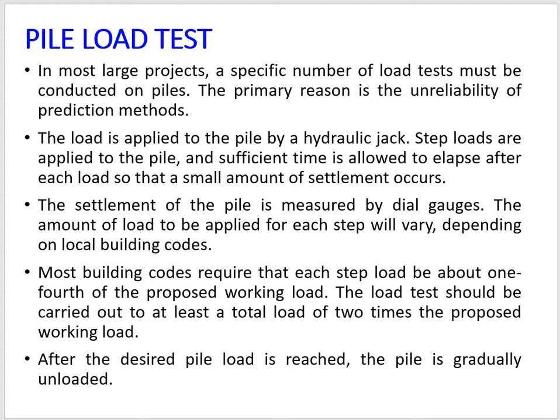In the field we have to do a number of pile load tests, because based on the soil strata and the vast area, you are constructing a lot of piles. So unreliability is a main thing that you can't predict. Also the pile load testing will be different. The soil strata is different, and the construction may change from place to place. The concrete quality won't be the same. So we do a number of tests for reliability. Only then can we assure the safe load for the pile.